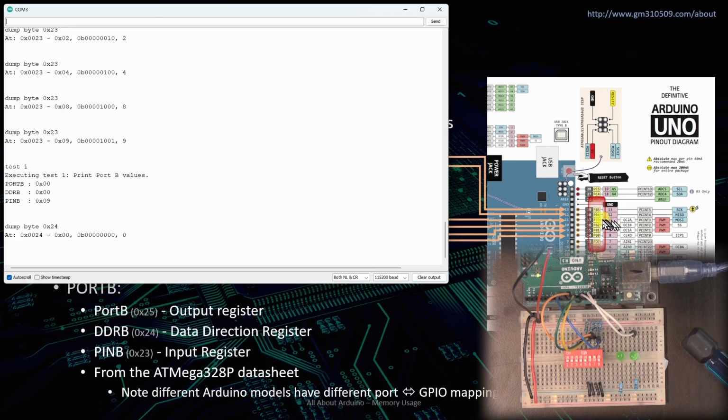Now, because these are connected to bits 4 and 5, that'll be the second half of this hexadecimal value. So this digit, or the low nibble, these half 4-bit groups are called nibbles. This low nibble is 8, and then the first bit on the port in the second nibble, bit 4, is 1, so that'll be, if you like, 10, and this one's 20, so 30. So what I'll do is set those 2 bits to output. So test 0, DDRB,